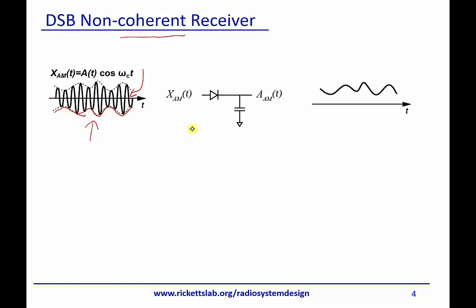And so a very basic one is a simple rectifier where we're just peak detecting. And you can see where this just peak detects and we get our signal off the back. Now, if you use this circuit exactly as it is, you would just have a DC voltage on the top here. In reality, there is some load off here that discharges the cap so that the signal can fall over time. But the basic idea there is we're just doing a peak charging.